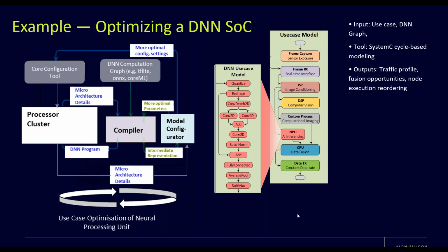Yep, this is absolutely critical. It'll tell you things like, is my cache subsystem or my on-chip memory able to hold the working set of whatever my workload is? Because if it can, you'll get good performance. If it can't, performance falls off a cliff. Or if you're streaming data, can you support that number of outstanding transactions through your interconnect? Things like that you will see in a simulation like this.